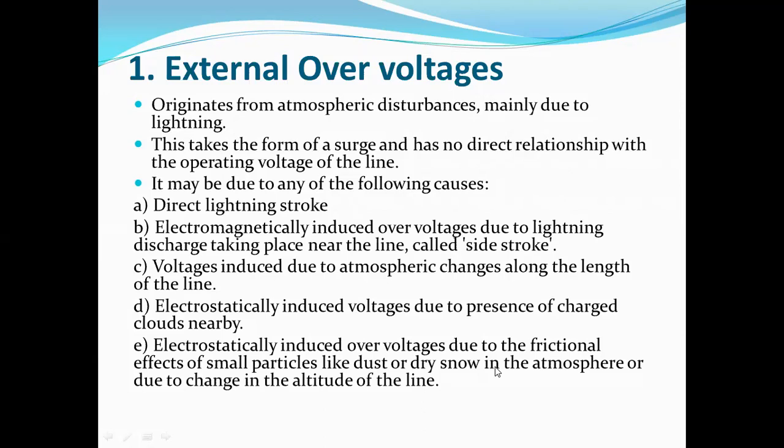Then second is the electromagnetically induced over voltages due to lightning discharge taking place near the line, called side stroke. So when the lightning stroke is discharging near the line, that is called the side stroke, and the electromagnetically induced over voltages will be there.